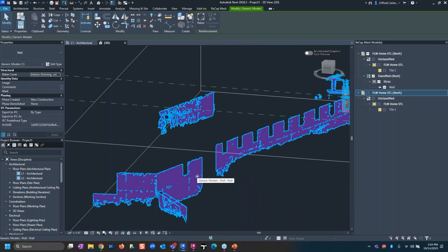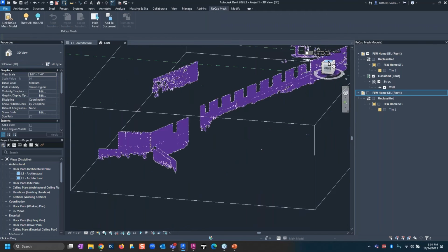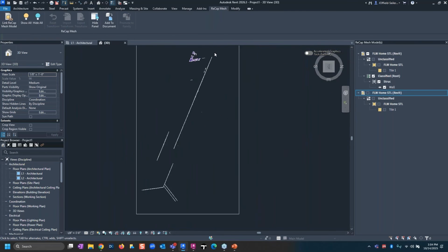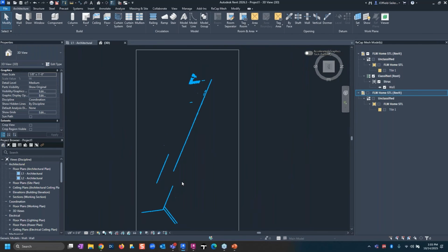The interior was not done, so there is not what we would see as a thickness value. It's just something that we could take into a top or side view and use that line work to snap our lines when we're using the draw walls, and just verify we're on that particular plane.